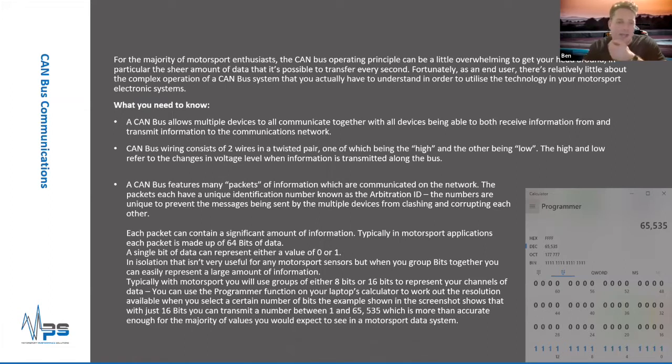Then once you have a CAN packet, there's a large number of possibilities of where you could hide your data within it. So if I'm trying to make my ECU send me throttle position, for example, there's an almost infinite number of places it could be hiding on a CAN bus system. If I don't know where the ECU is sending it, it's very, very difficult for me just to rock up with my data logger and try and decode it.